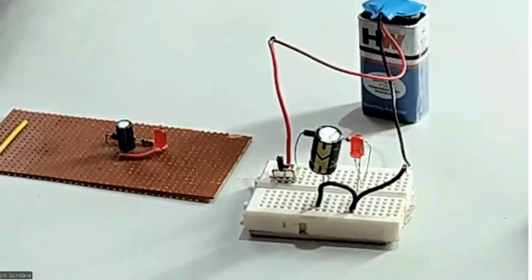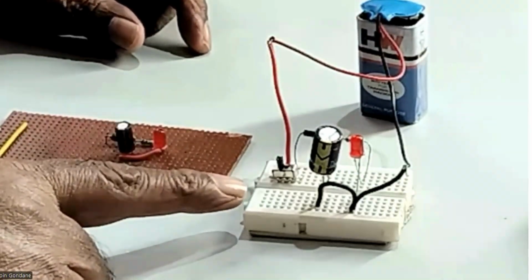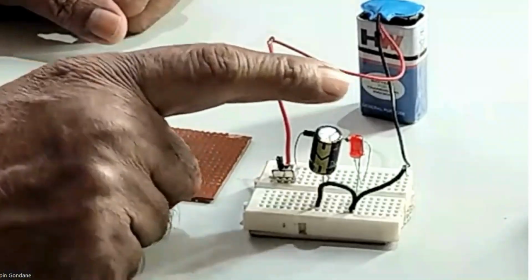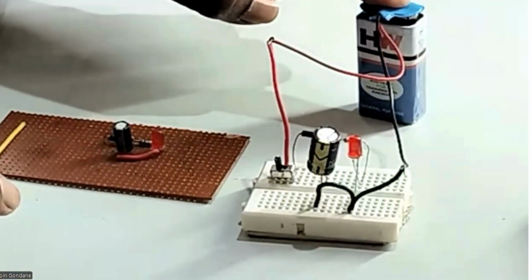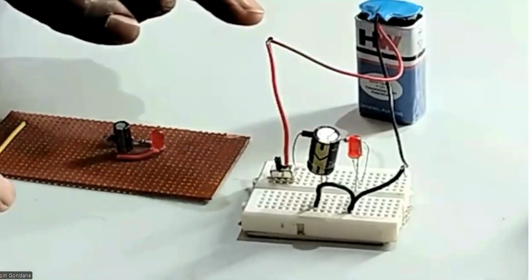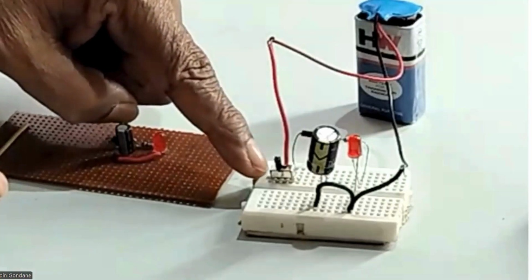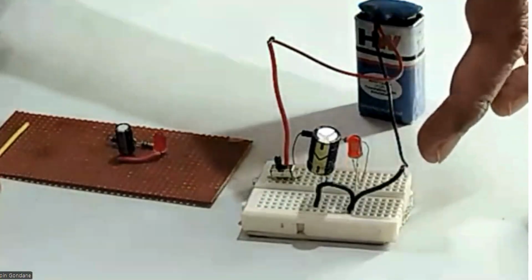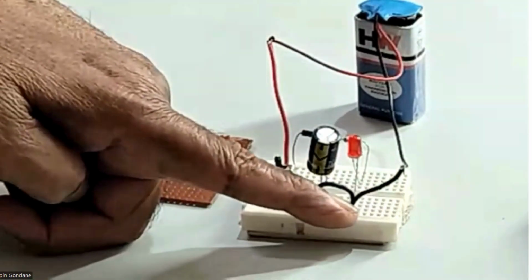All right, friends and students. So we have come to the lab. You can see here, not on a PCB, it's a breadboard. On the breadboard, I have fixed the same 5 components: diode, resistor, LED, capacitor. And there is a supply voltage, that is a battery. From the battery, 2 connections are coming. This is the positive. I have given it to one end of the switch, and the other end of the switch I have given to the diode. And this is the negative. I have connected this negative common to the capacitor and this LED.